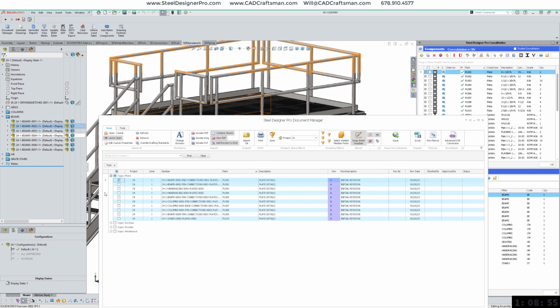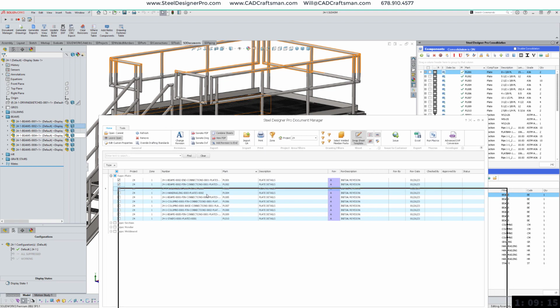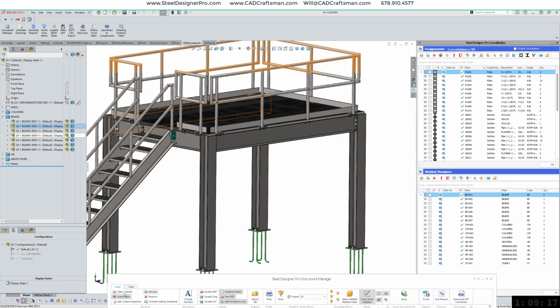To allow rapid checking of drawings, click in the left column, hold Shift, and click a lower drawing to select a batch of drawings. Select Open Commit to process and leave the drawings open. You can quickly check the placement of dimensions and clean up details. Rebuild, save, and close each of those drawings. You can use this process to quickly check all of your drawings by opening as many as your computer allows.